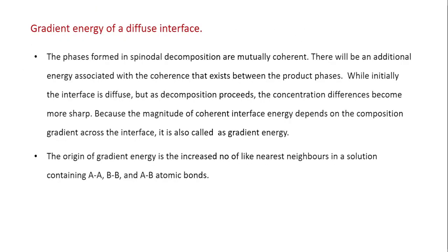Gradient energy of a diffusing interface. The phases formed in spinodal decomposition are mutually coherent. There will be an additional energy associated with the coherence that exists between the product phases. While initially the interface is diffuse, as decomposition proceeds the concentration differences become sharper, so the interface becomes less diffuse.